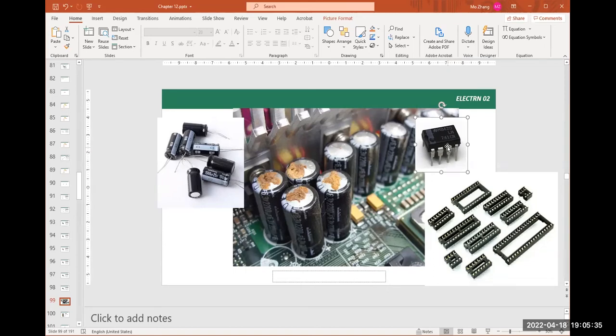We cannot solder this on the board directly because the soldering gun reaches, let's say, 300, 400, 500 degrees, and when the tip of the soldering gun touches here, the high temperature can burn the materials inside. Those are silicon materials inside the chip. It can burn that easily. So to prevent all this from happening, we put this on the board first.